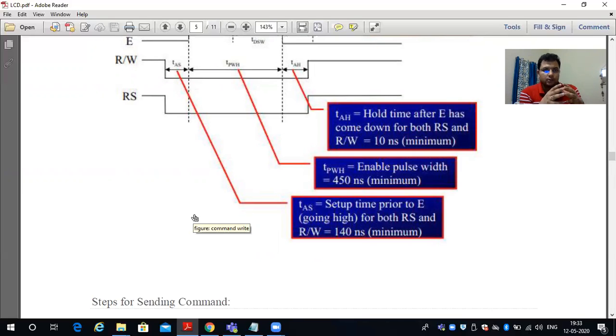Once we have configured those pins as output pins, anything which we want to display over the display lines, because there are 2 lines, we have to send the data over the data lines, and at the same time control it using RS, read write and enable. So what should be the procedure? First, there must be data over the data line. So first we will send it.